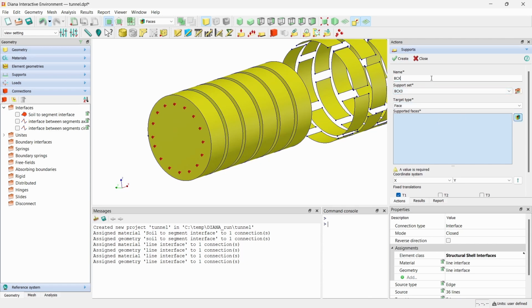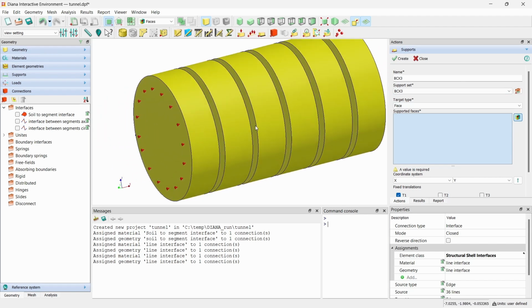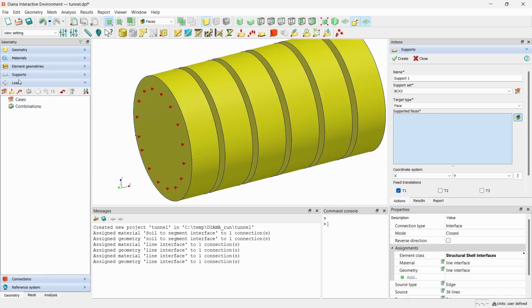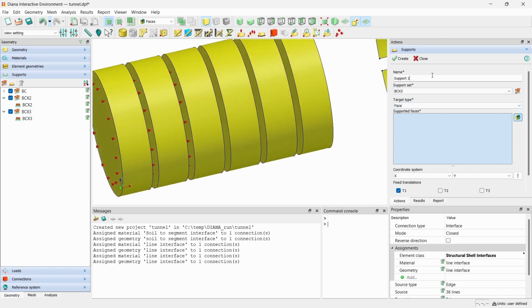So we have to select one side of the excavation soil each time to simulate the supporting of the TBM machine once with different phases, for example, to simulate the progressing of your excavation and installation. And we will need to do it for the rest of the phases as well.